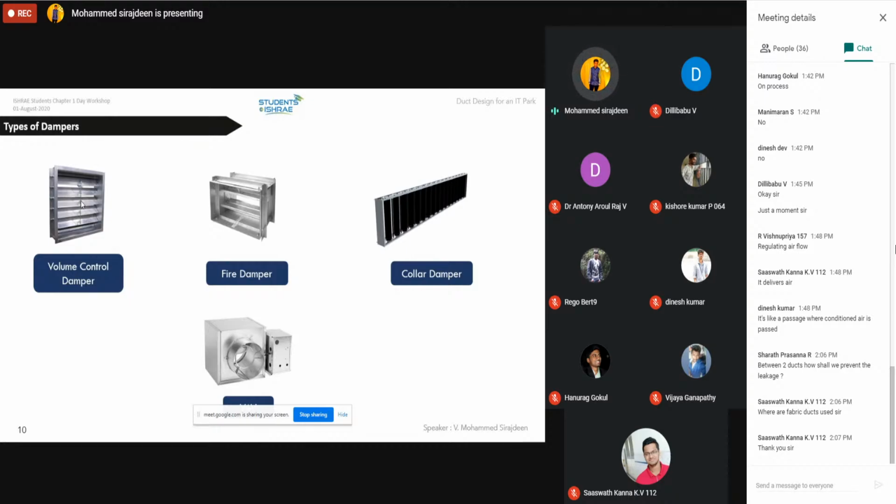No. Even if we size the duct for proper velocity, head loss, or as per design, without a volume control damper the air will not go as per the measured amount. So some rooms may receive more air, and some rooms will receive less air. The first room may receive more air, and without controlling the air, the room will get cooled in a very short time. So he cannot sit there for a longer period. What will happen to the fifth room? The air will not go there because the entire air has gone into the first room. So to avoid such cases,